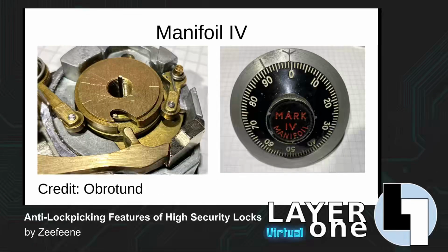And then we have the Manifoil Mark IV, so this was a British Ministry of Defence lock, and it uses a cunning two-part drive cam. This drive cam actually has two levels to it that need to be aligned in order to create the gate, as we can see here. But it also has these two rather devious rollers that make it very, very difficult to tell the difference as to whether or not you're trying to get information from the nose on this lever, which is actually useful, or if you're just working with one of the two specially designed rollers. That can be very, very tricky to work out indeed.